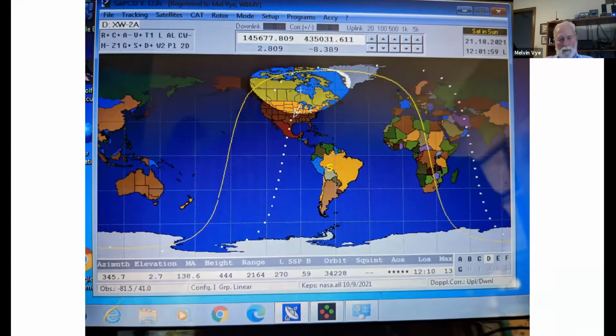One of the reasons that we put these satellites in such a low Earth orbit is that we're not allowed to keep them up forever. We have to prove that this satellite will destroy itself in 30 years. And by putting a satellite up this low, every time the satellite gets hit by a molecule of air, it slows down. When it slows down, it drops into a lower orbit. Eventually, it drops into an orbit that's so low that it burns up on reentry.